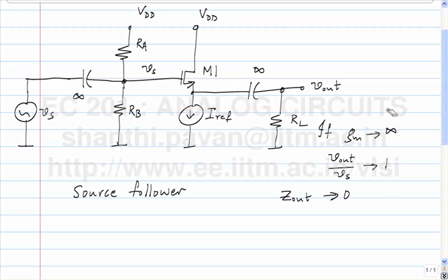Okay, so we know that the transistor will get out of saturation if the drain goes 1 VT below the gate. But here the drain is not going anywhere. It's sitting at VDD. So the moment the gate goes one threshold above the drain, the transistor will get into triode. That's bad. We know that. On the other extreme, what happens? The drain current of the transistor could go to 0, in which case the transistor is cut off, and that's bad too. So we have to figure out